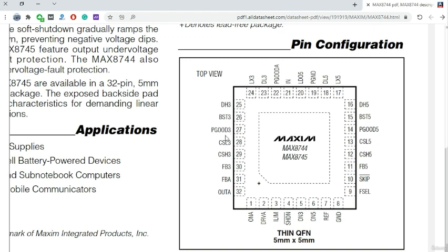Here we have the power good 3. When 3.3 volt is generated, a signal will go to the SIO from pin 27 to inform the super IO that the 3.3 volt is generated. The same applies for the 5 volt.